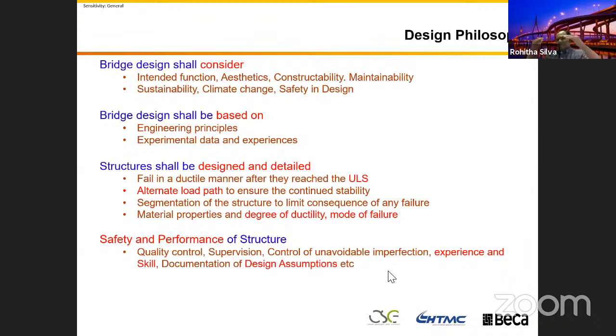I think that if you are building a bridge, it's not that easy for you to construct the bridge deck, because we are using concrete, pre-stressed concrete elements. They are not short length, they are 25 meters, some 100 meters in length. So these elements have a significant deformation pattern. I think they are very difficult to predict. And then the experience and skill. When you are a bridge designer, the bridge design experience and skill is very, very important.